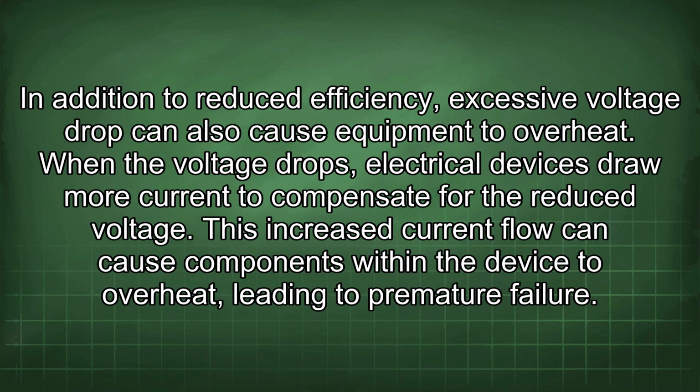In addition to reduced efficiency, excessive voltage drop can also cause equipment to overheat. When the voltage drops, electrical devices draw more current to compensate for the reduced voltage. This increased current flow can cause components within the device to overheat, leading to premature failure.